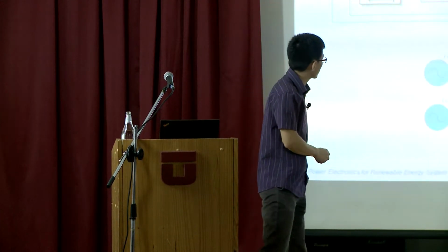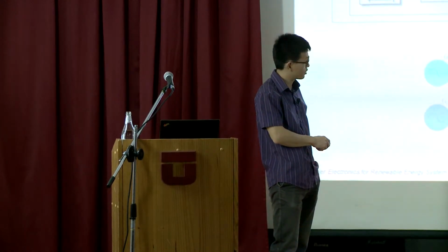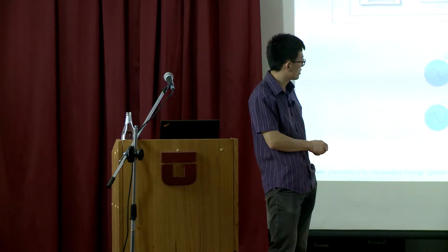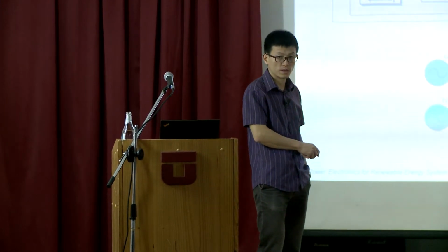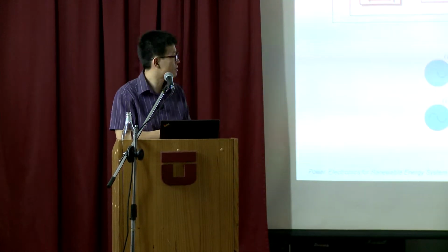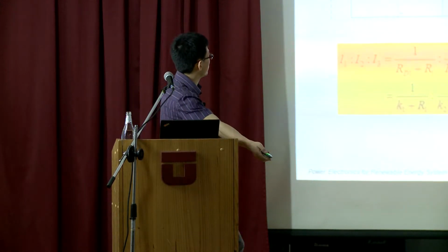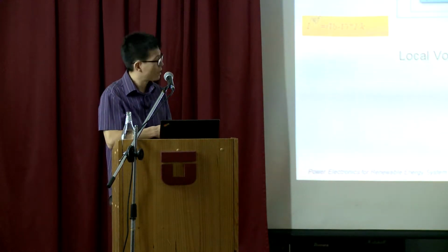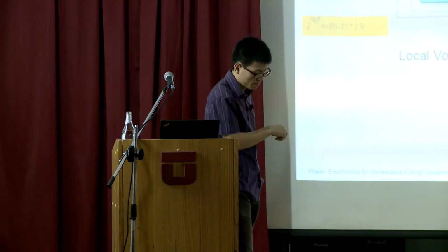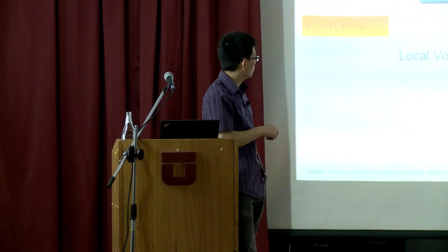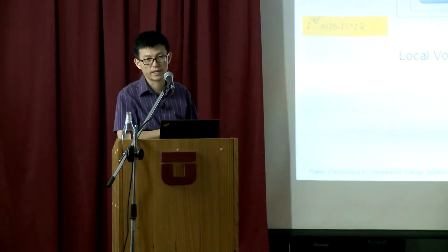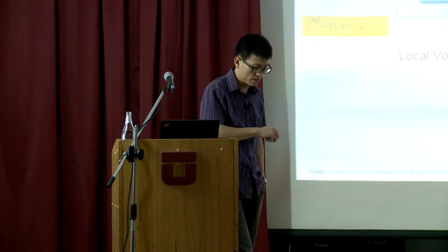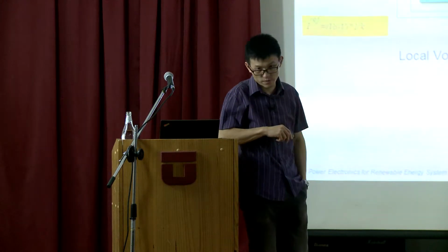Here we go. So you can either feed back the local voltage to your droop, or you feed back the common DC bus to the droop. So you end up with two different concepts. I think most of the literature before mainly used the local voltage feedback. So our colleague proposed a kind of global voltage feedback.